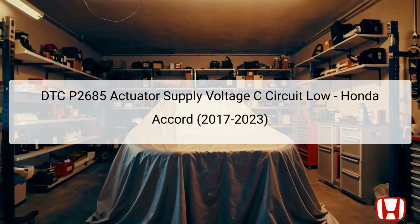The Diagnostic Trouble Code, DTC P2685, indicates a low supply voltage in the actuator supply voltage C circuit, affecting the vehicle's transmission control module, TCM. This issue can lead to various symptoms, including erratic transmission behavior or malfunctioning actuators, which can impede the vehicle's performance.